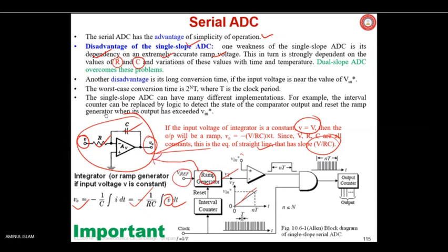Your reference voltage is fixed. The reference is a fixed voltage. So if V here is fixed, then is it not this integration value is this? Yes or no? Yes, sir. Okay, good. A negative sign comes because it is inverting configuration.